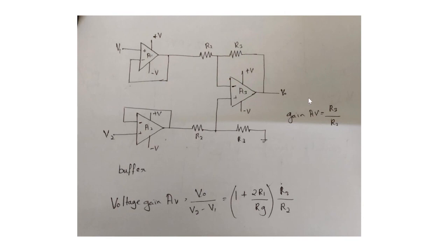This is the circuit diagram of an instrumentation amplifier. A1 and A2 form a buffer circuit, and the bias current of the instrumentation amplifier is determined by the op-amps A1 and A2. Here R1 and RG are removed, which results in a full series negative feedback path, and the gain of A1 and A2 will be unity.